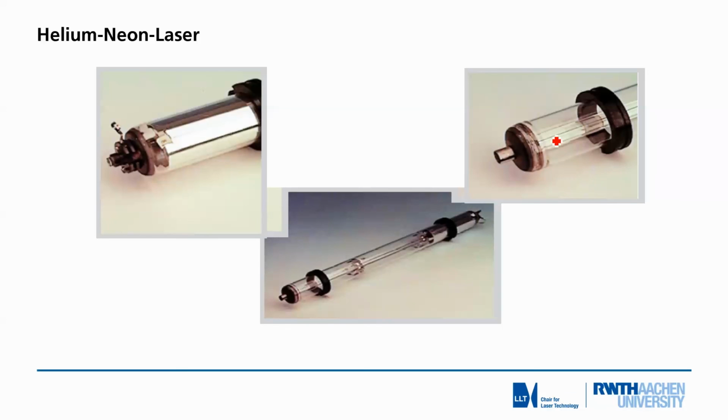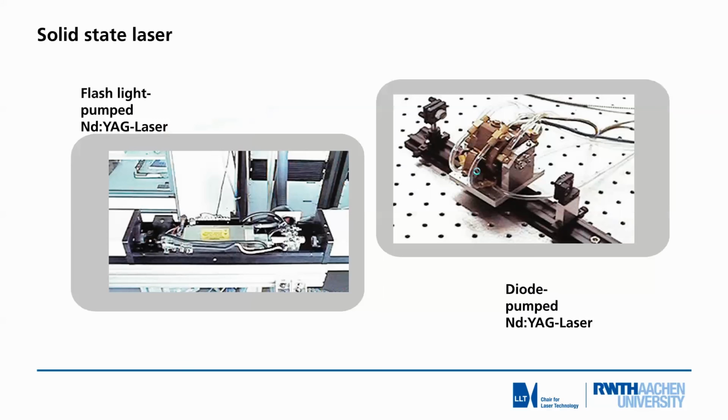This metal holder is connected to the glass tube, so we have a monolithic structure, and the resonator is mechanically stabilized simply by being soldered onto these mirror mounts here, and the mirror itself sits here right at the end, and the adjustment is just done by displacement of that mirror. This is a soft metal, so it just can be bent a little, and so we adjust the laser, and that's it. So very straightforward, very simple way of setting up a resonator.